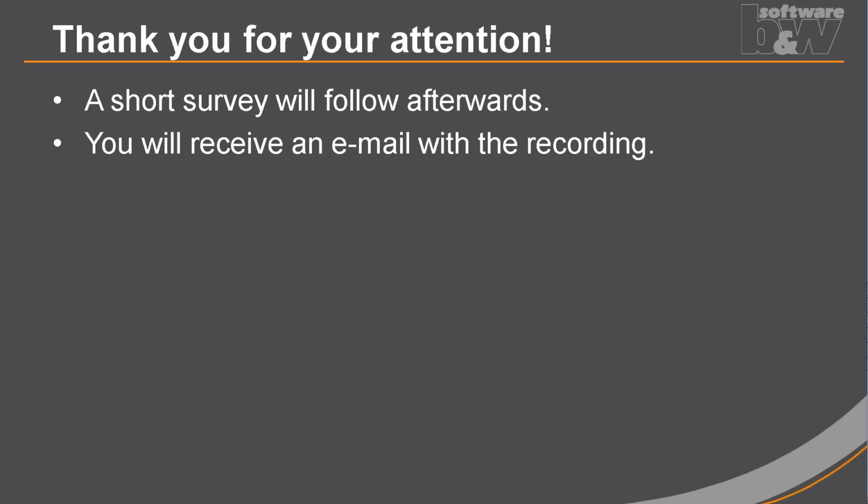You can open the drawing or the assembly, and at the beginning, SMARTUpdate only checks the assembly. If you also want to check the structure, there is a button to load the subcomponents, and the whole structure of the assembly will be loaded and treated just like if you would open, check and correct any part individually.